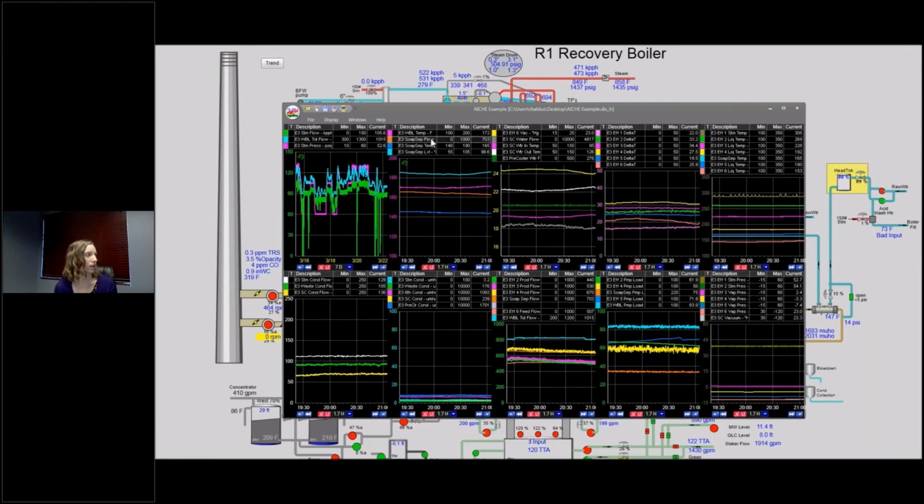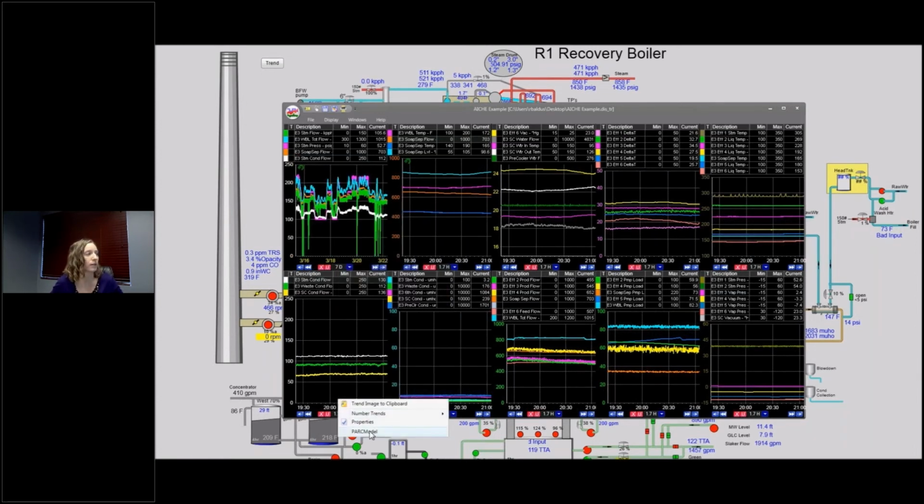So I'm going to focus in on that trend, and I'm going to drag in a few other tags that might have an impact. The idea is we want to replace that green tag with a modeled version. So I'm going to go ahead and drag all the tags I might want to consider. Then if I right-click and launch our Park Model tool, we'll create a PLS model. That's the version that lets you predict a tag.